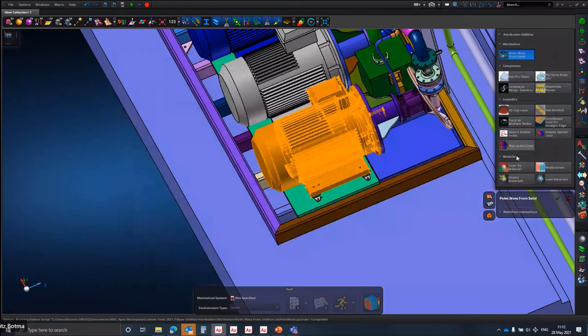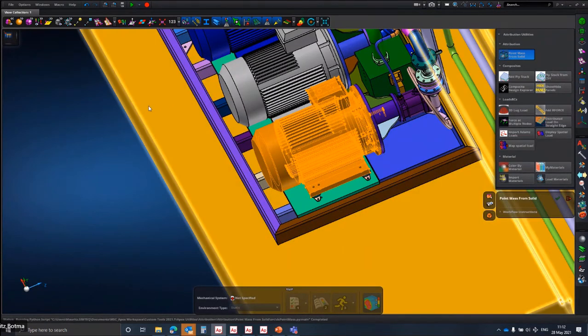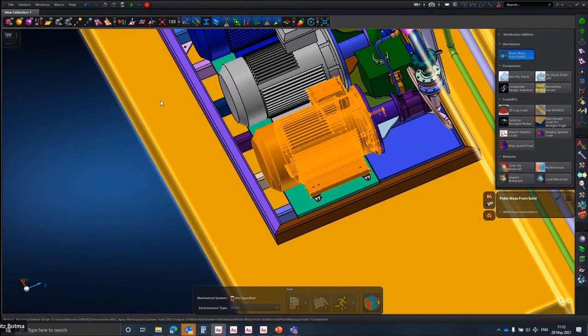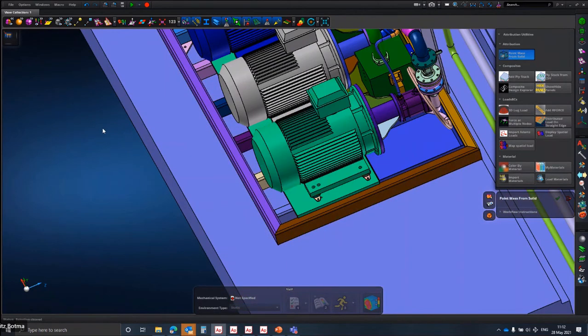This is another thing that I just want to mention: if the tool does not work, please go and look in the log file, because often you will find the reason why that specific tool does not work there, and then you can simply change it, and the tool should work as expected. So I still need to assign material to my different geometry pieces in my assembly.